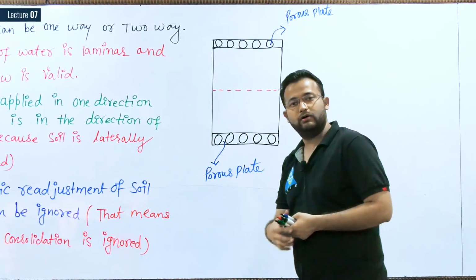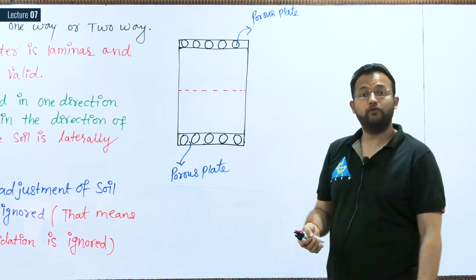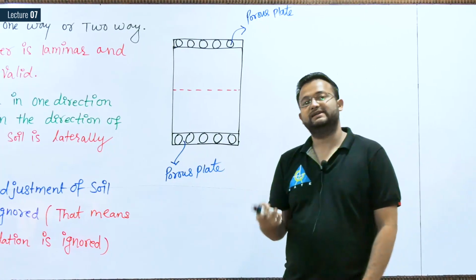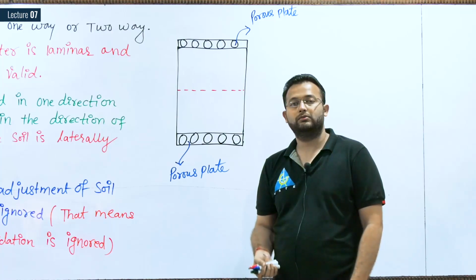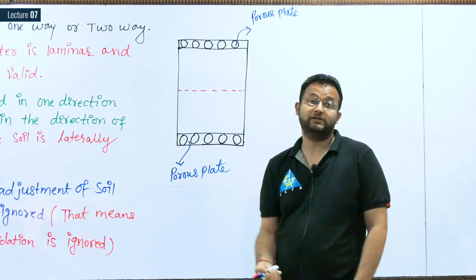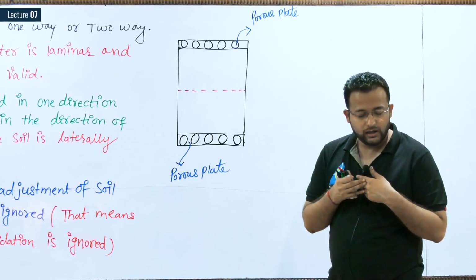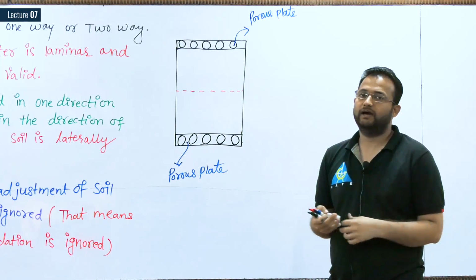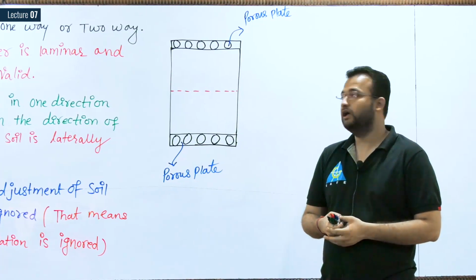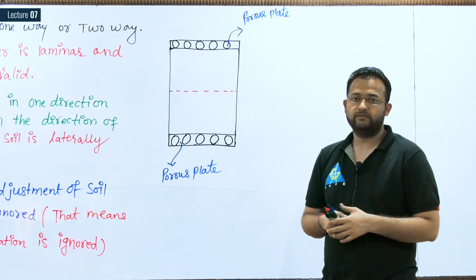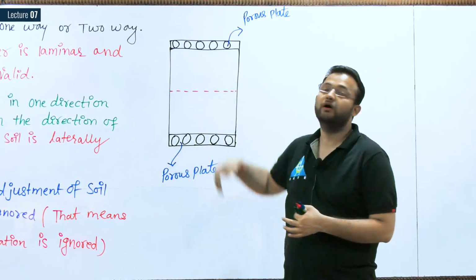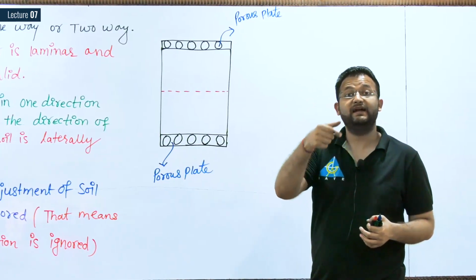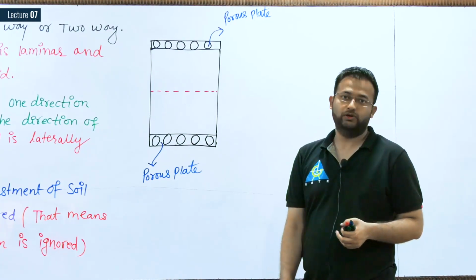I have already discussed that this study shall be done for clay soil only, because sand has high permeability. Consolidation should not be studied in sand, it should be studied in the case of clay, because in clay the water drains out taking a lot of time and showing a lot of settlement in the soil. So in the mold I have filled the clay soil, and on the top and bottom we have the sandy soil in the ground actually.